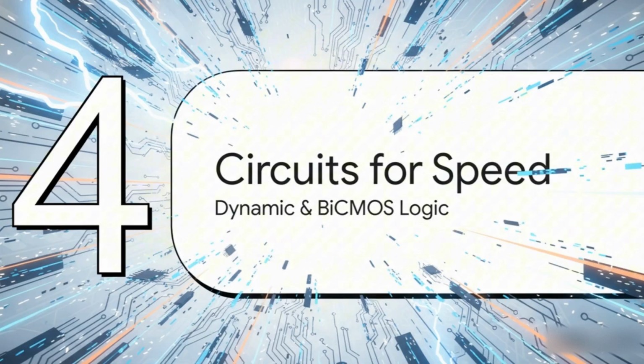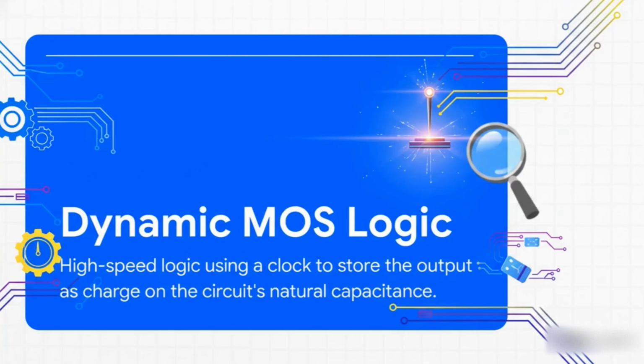All right, now we get to the fun stuff, the speed demons. When your only goal is raw, blistering performance, making your logic switch as fast as is physically possible, you enter the world of dynamic logic. This is definitely a high-risk, high-reward kind of strategy. Now, unlike all the other circuits we've looked at, dynamic logic isn't static. The output isn't always firmly tied to power or ground.